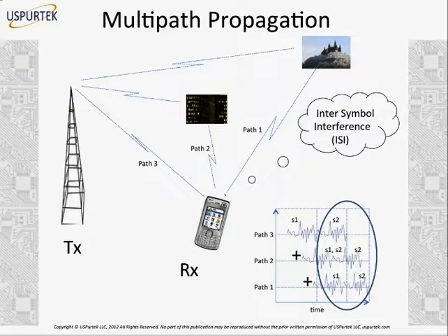What this means is that if we are receiving data over the air and all this is happening due to multipath propagation, the receiver will see the adjacent symbols superimposed and it will appear as useless or corrupted data bits, and we will miss data. So the challenge for mobile wireless system design is to remove or avoid the ISI, the inter-symbol interference.